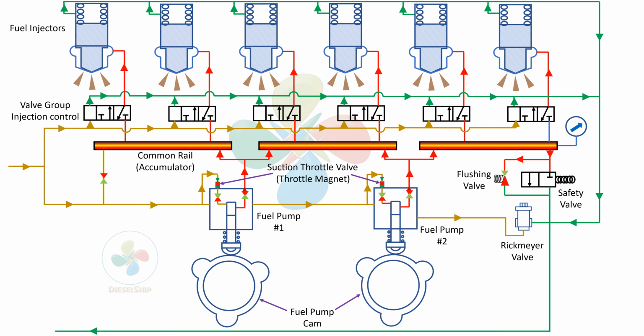It maintains the fuel pressure through the engine, right? It connects the inlet and outlet. In Sulzer, we call it valve block or pressure block or pressure regulating valve. Whatever you call it, it is a simple spring-loaded valve set to maintain certain pressure in the engine, right? If the pressure is too low in a traditional engine, the fuel pumps go into starving mode, where a lot of consequential issues happen.